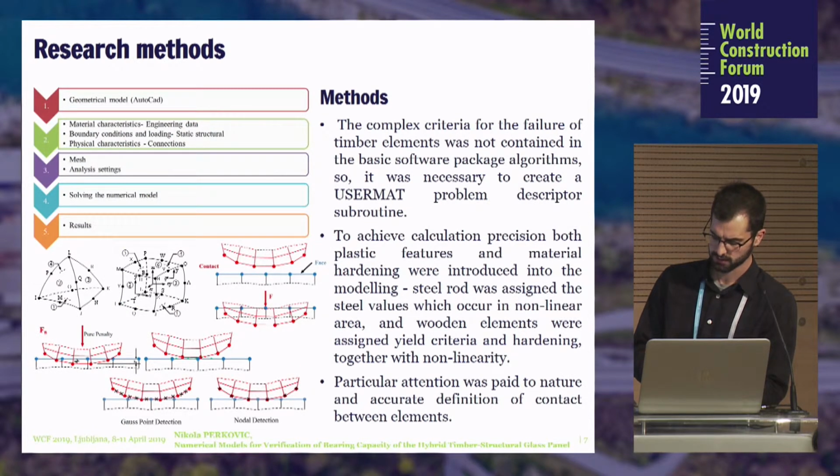Some basic steps: first we needed to make a geometrical model. I made that in Autodesk Inventor. Then the most demanding part was defining a contact between the adhesive layer and timber.